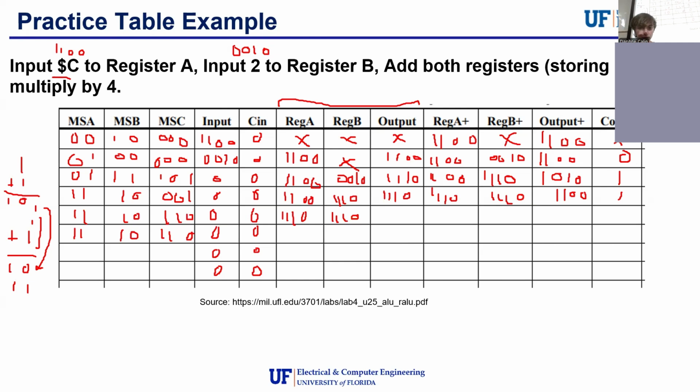So we shift left once, put it into A, shift left again, and put it into A. So if we have the output, a shift left is going to add a 0 in the beginning. So it'll be 1, 1, 0, 0. And B will stay the same, 1, 1, 1, 0. And we can actually see that this is the same as, oh, we haven't done this addition before. So I'll just do the addition again. So first bit is 0, second bit is 1.